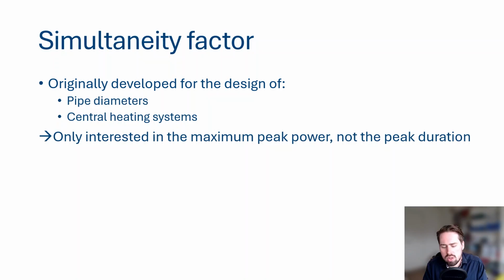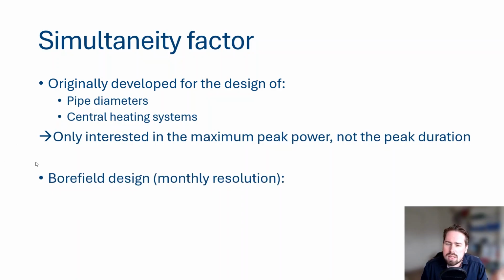So you just need to know, okay, if we have a certain amount of connected users, what's the maximum amount of peak power that can occur? It does not really matter originally or historically what the duration of that peak was. If it occurred for 1 hour or for 100 or 1000 hours, that was just a matter of the fuel or the energy demand. It was not that important how long the peak duration actually was. But for our geothermal bore fields, this is important.